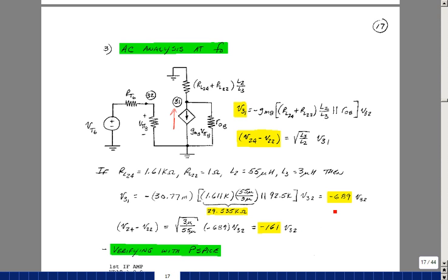So we get a much bigger gain out of this stage of 689. Again, it would be negative. Magnitude would just be the 689. And then the transformer would step that down to about a gain of 161. So this is going to then be passed to the second IF amplifier. It will be filtered again and amplified. So we'll be able to get enough gain to be able to hear our received signal.